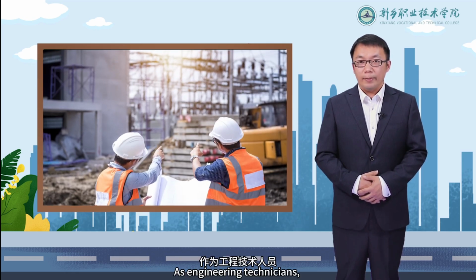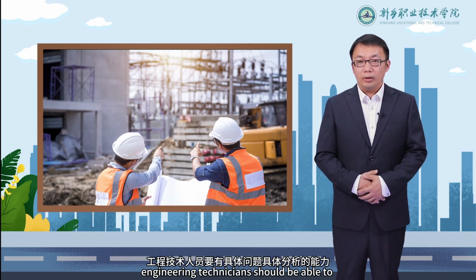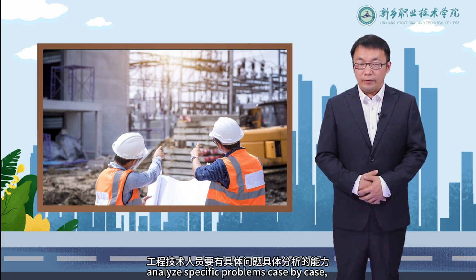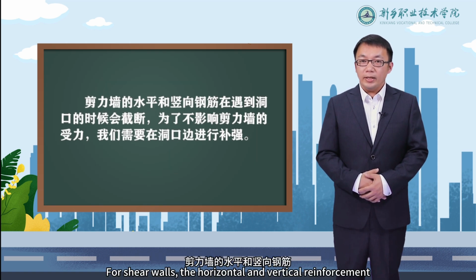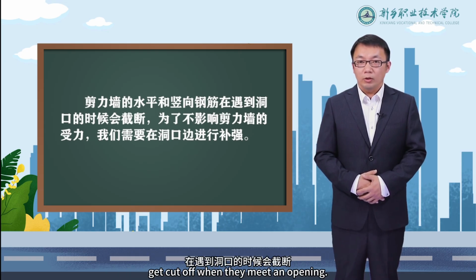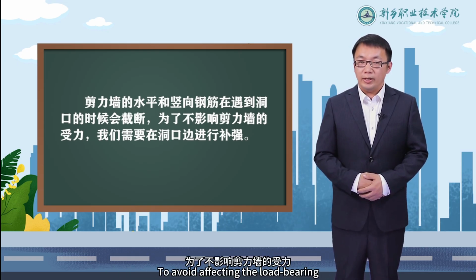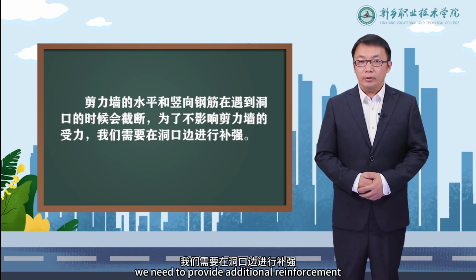As engineering technicians, we face different engineering problems every day. Engineering technicians should be able to analyze specific problems case by case and adopt appropriate methods based on actual conditions to solve problems. For shear walls, the horizontal and vertical reinforcement get cut off when they meet an opening. To avoid affecting the load-bearing performance of the shear walls, we need to provide additional reinforcement around the opening.